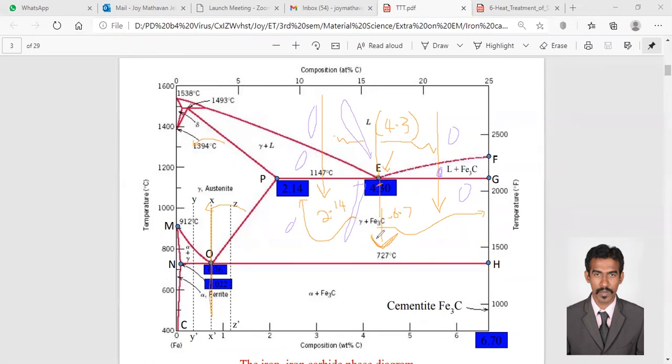So that's why I told you these temperatures and compositions are very important while drawing this diagram. Even if there is a 0.1 weight composition difference, between 4.31, which is in this region, and 4.29, that is in this region, anyhow it is going to accommodate some parts from here and some parts from here, but we do not need this. So that way we are going particularly through this point. There we can obtain the exact phase transformation from this region to this region, with no disturbance due to these regions.